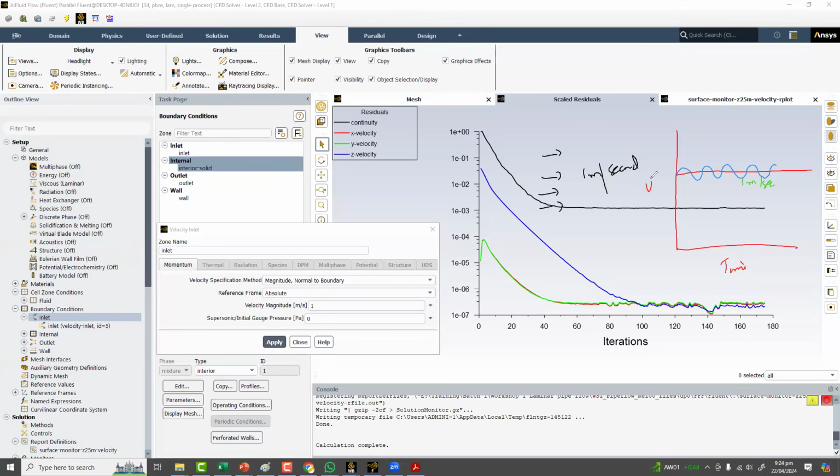On one side, the change may be 0.1 meter per second. So the change from the mean value, which is 1 meter per second, may be equal to 0.1 meter per second. This deviation from the average velocity is my fluctuation. This is the fluctuating component of the velocity: how much fluctuation we have in the velocity from the mean value. This is a change in the velocity at every location. So the maximum change we have is 0.1 meter per second.